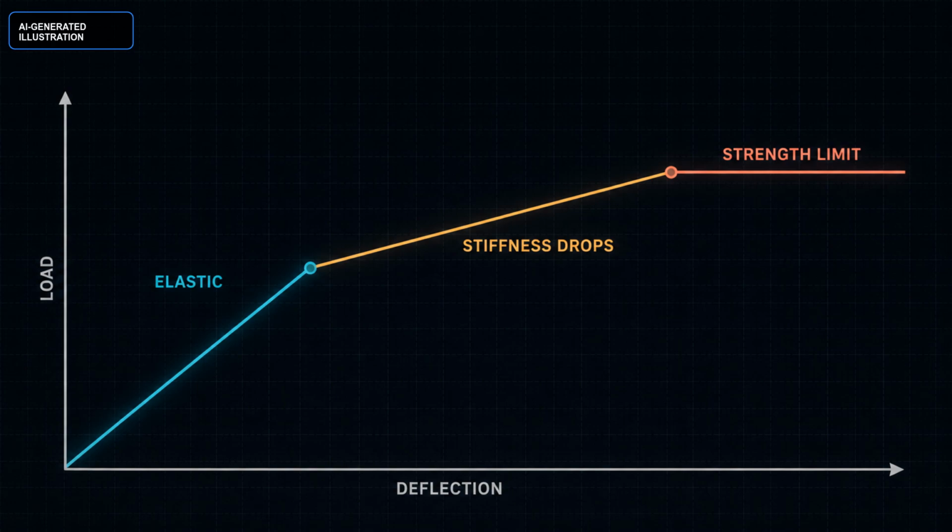The most useful warning is often a change in the load deflection response. An elastic girder follows a roughly straight line and returns when the load leaves. After cracking, yielding, corrosion-related section loss, local buckling, or a damaged connection, the slope can fall, and some deformation can remain. A redundant bridge may redistribute load after one member is damaged. A non-redundant path may not. That is why "it is still standing" is not a complete diagnosis.